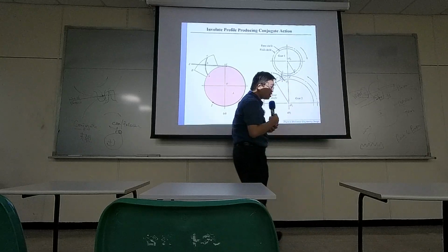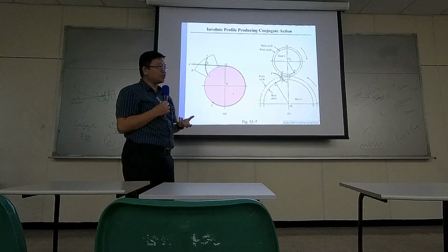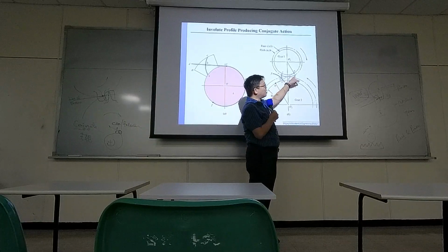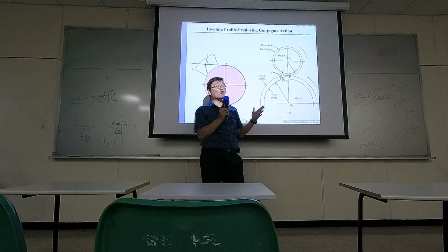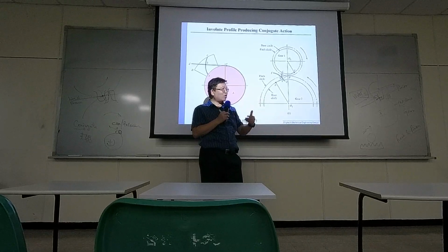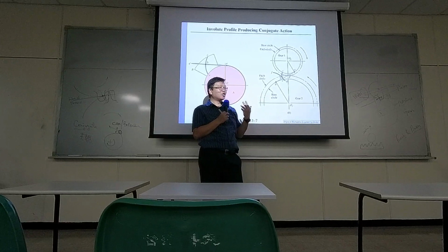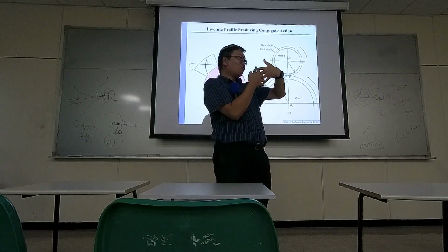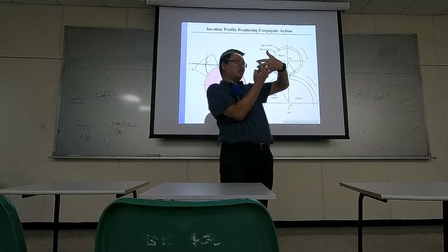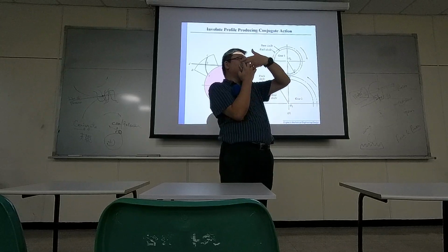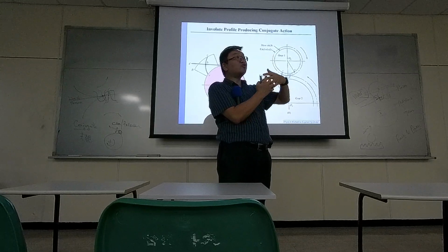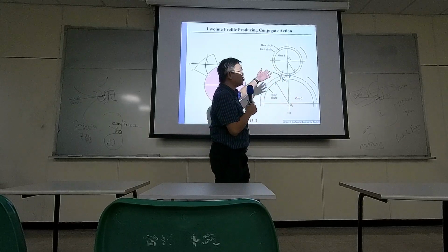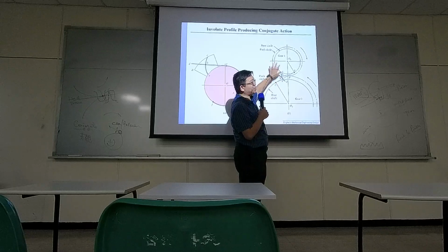Okay? And for engine gear designers, of course they want the contact length to be longer because it will make the gear pairs more stable. Because if you have a longer time for the gear teeth to be contacting with each other conjugately, then you have good transmission of the pressure from one side to the other side.